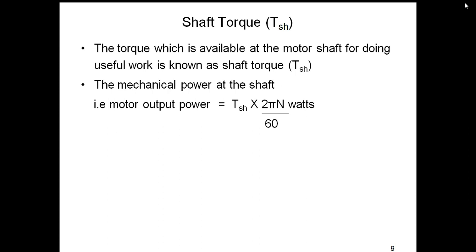The mechanical power developed at the shaft will be given as TSH into 2 pi N by 60 watts.